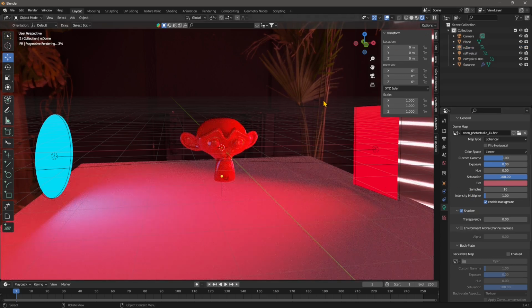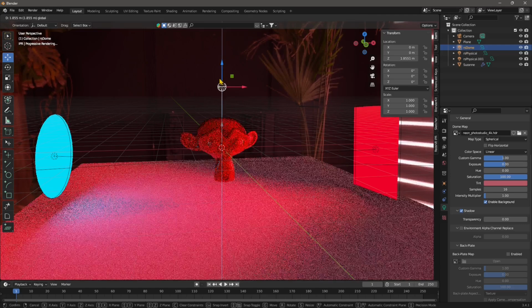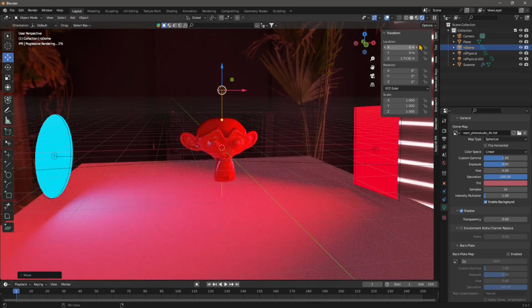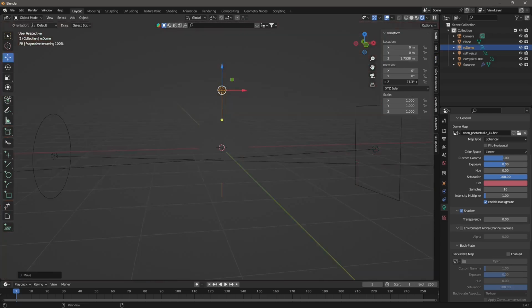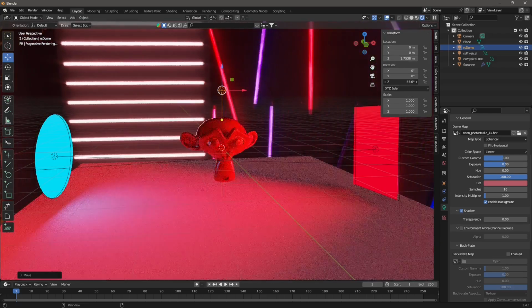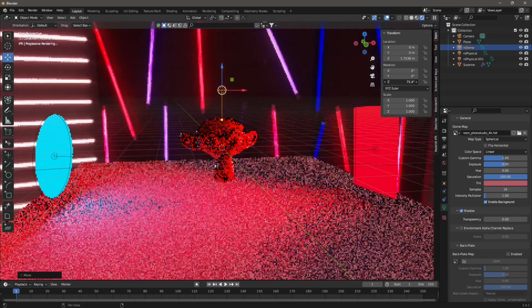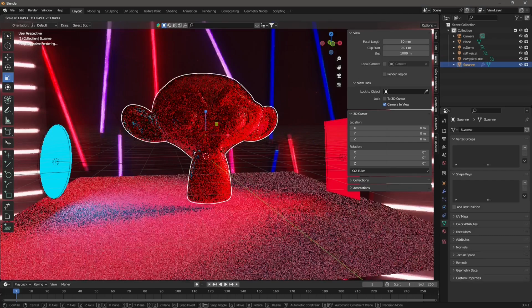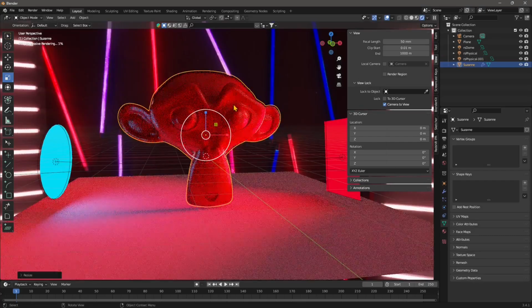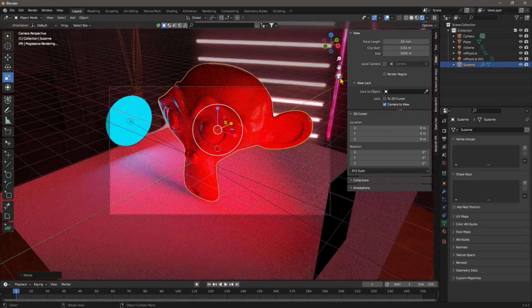Now this is a light, which means that if you select it in the object panel there, you can also rotate it. I can move it around. You can see there it's visible. And then in the transformation tools again, if I rotate this using the Z, I'm gonna rotate the light, which means rotating the image because the lighting here is coming from the image. So this is the quickest render you can do using just an image. It's called image-based lighting, and it's the quickest way you can do a render in Blender using Redshift or any other render engine.